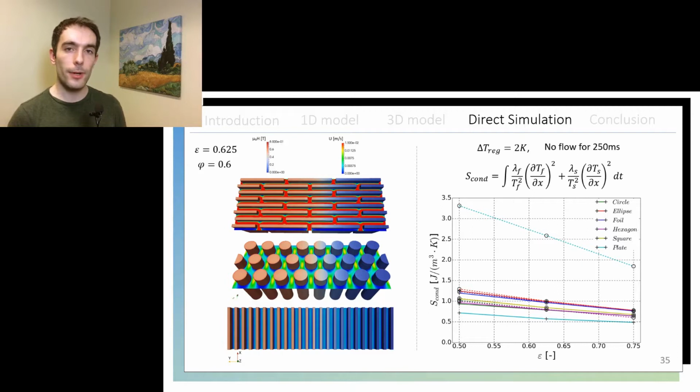So this larger pressure head and Nusselt number for the staggered cases or the larger tortuosity cases comes from an increase in the local velocity of the heat transfer fluid. Since we're keeping constant the mass flow of those surges and the tortuosity is higher, so the distance that the fluid has to travel is larger, the local velocity has to increase. This is exemplified in the left side of the slide.